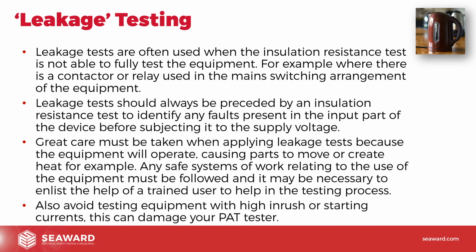Now, if it's going to draw that through the PAT tester, that could actually blow the fuses in the PAT tester. It could damage the relays in the PAT tester. And we have had this in many cases where people are damaging the PAT testers and they don't know why they're doing it. They don't know, oh, it just keeps blowing up, it just keeps going wrong. And this could be they're testing things like large circular saws, pressure washers, big industrial pressure washers. Lighting has high inrush current. So big studio lights, big theatre lights, things like that, where when you first turn it on, the current suddenly shoots up to 50, 60, 70 amps maybe. That's being pulled through the PAT tester.